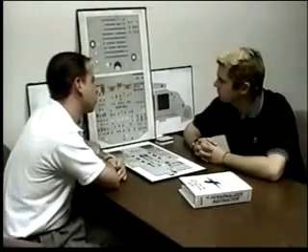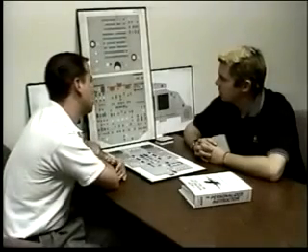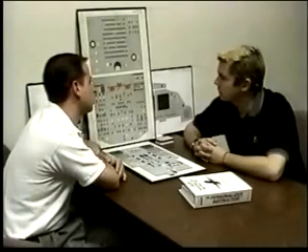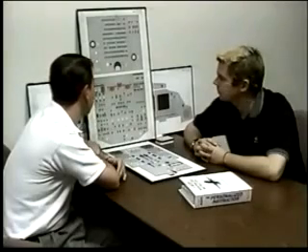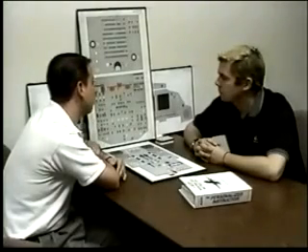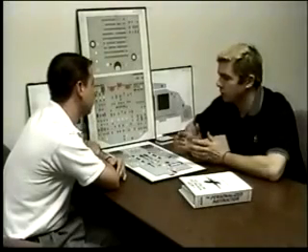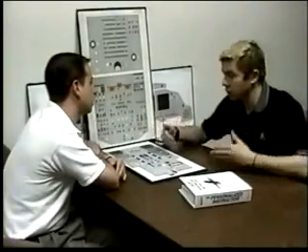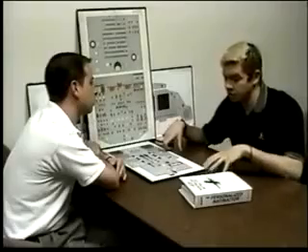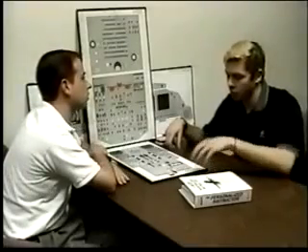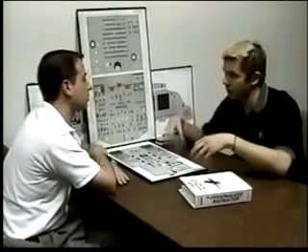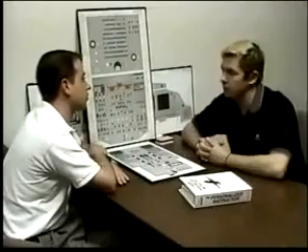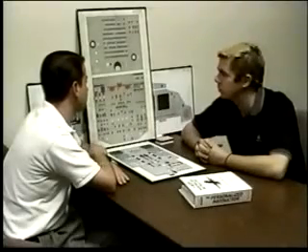When would the transfer valves open up to allow the outer to spill into the inner? When it senses less than 1650. Okay, is that both of them have to get to 1650 or the first one? No, whichever one gets to 1650. There's 4 valves, 2 in each tank, and they're kind of cross-related. So if I get below 1650 in the left wing, 1 valve in the left and 1 valve in the right will open up and will allow the fuel to flood into the center tanks.